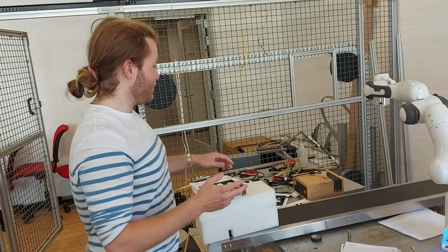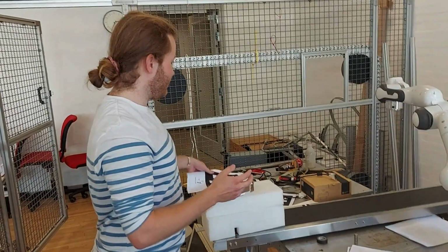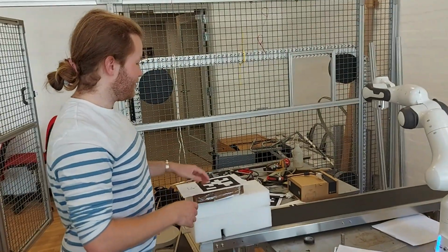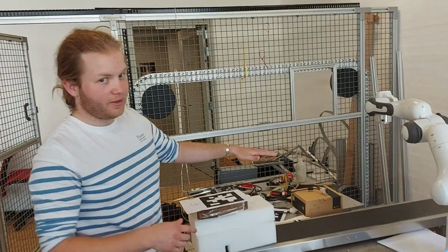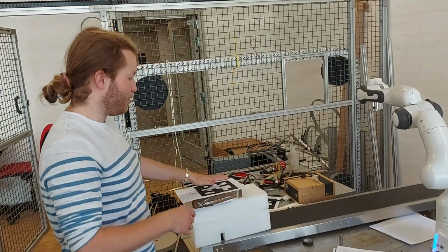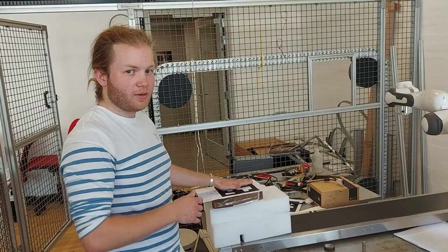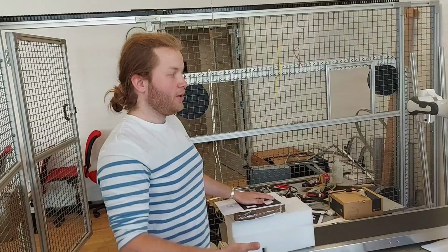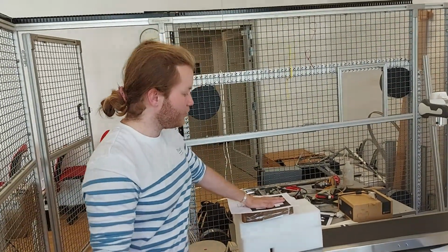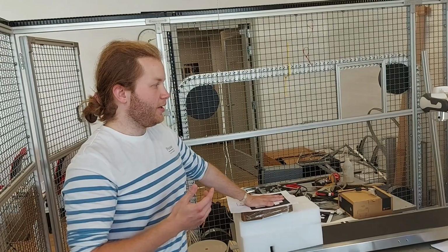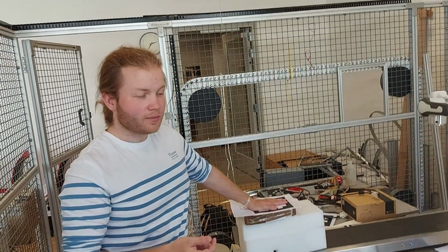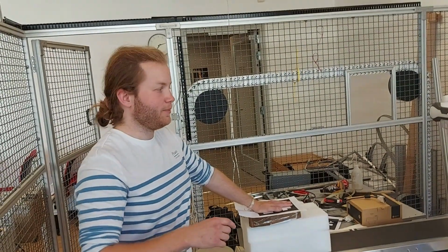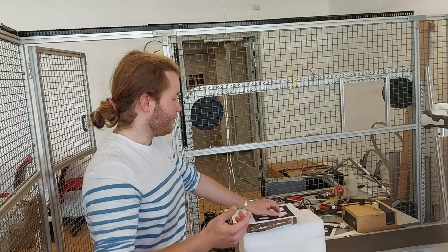Normally, when I turn on the conveyor belt to pass the ArUco tag through, the AAC would move to right above the tag and slow down. But when I included the velocity reference, it had a tendency to overshoot. And the problem with overshoot is that when it bumps into this stack, it gets, I want to say, a torque error because it experiences torques externally that it isn't expecting, and then it freezes.